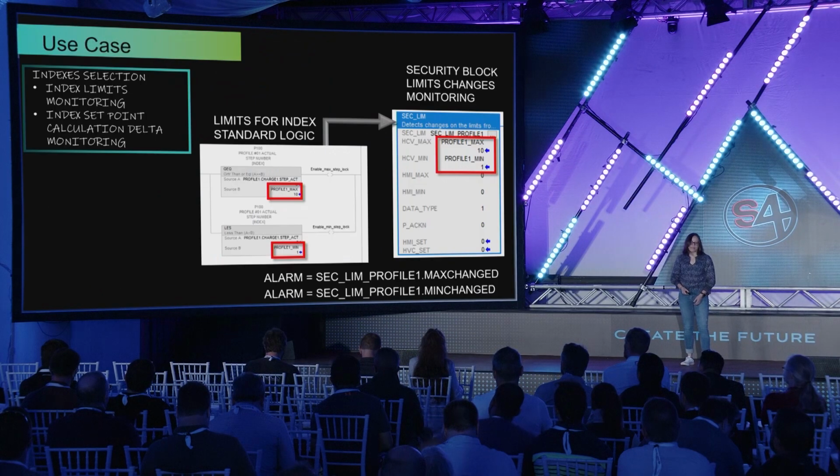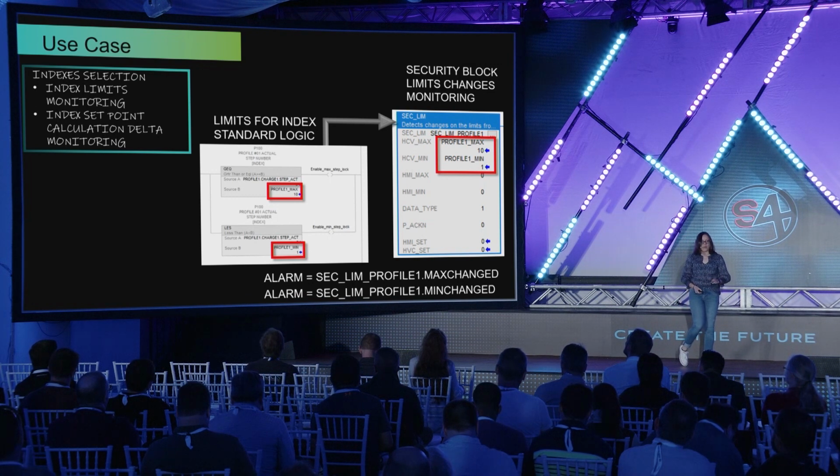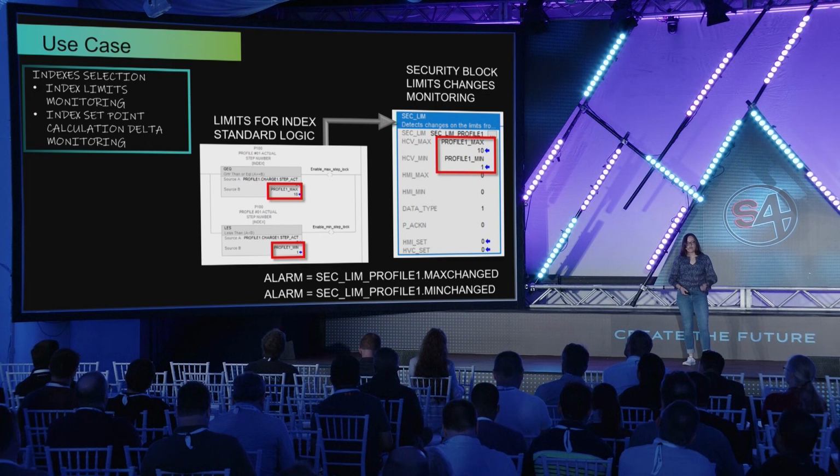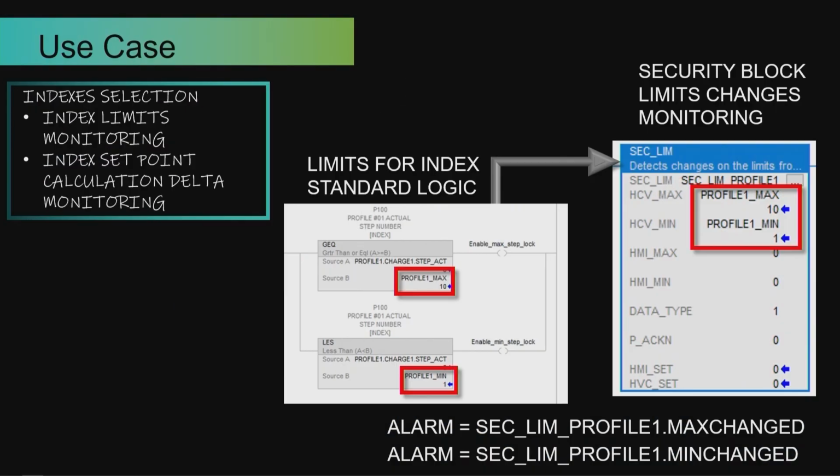So we have the process operation. Actually, we have 2 blocks. Those 2 blocks are for limits and also for Setpoint Delta. This one you can integrate into the process, but it is going to be for security. In this case, what we created is a profile for the electric furnace, so we have to have those limits hard-coded. That is something that is also mentioned in the top 20. You can see that they will tell you you have to hard-code it.